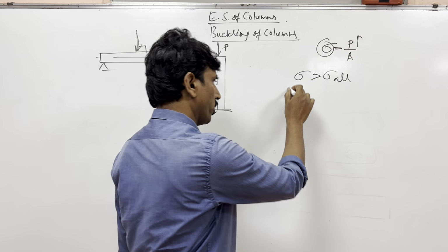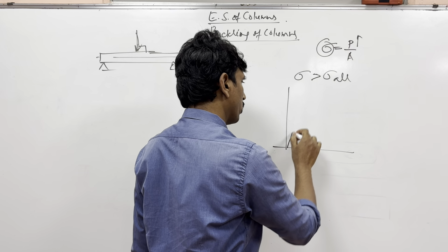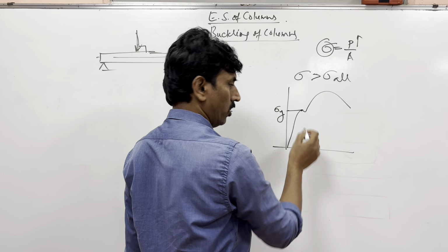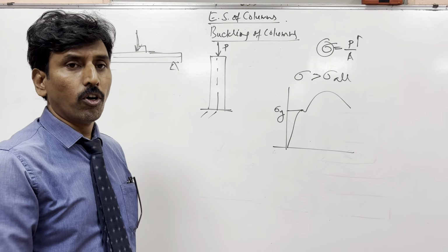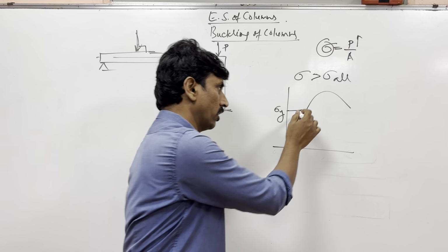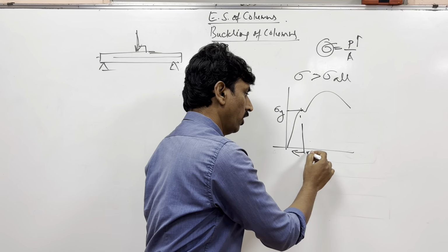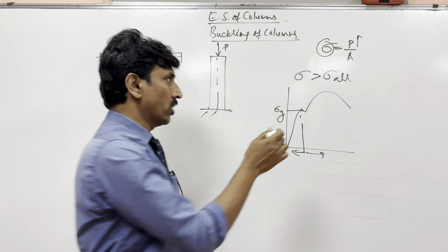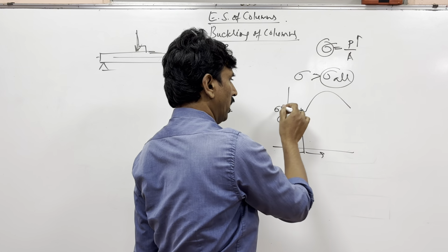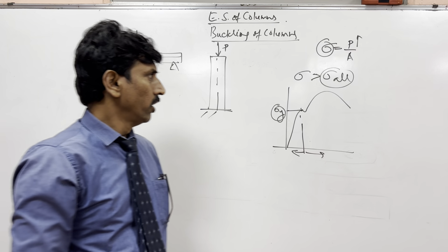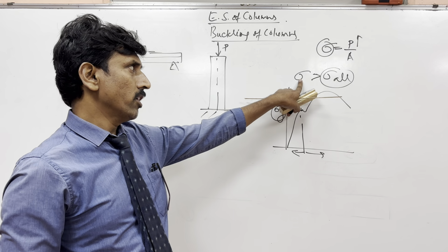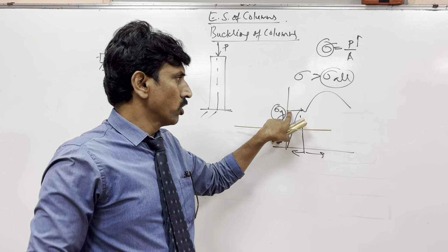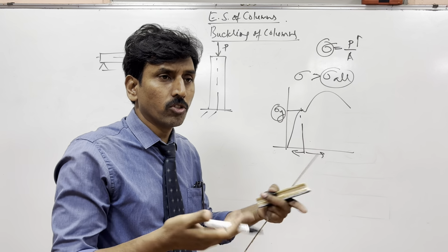We have seen the stress-strain diagram, something like this. This is the yield stress, where the material plastically deforms, so it loses elasticity at this point. Up to this point it is elastic, and beyond this point it is plastic. The allowable stress and yield stress are the same. The stress in the material should not go beyond this yield stress. If it does, the metal would have changed shape.